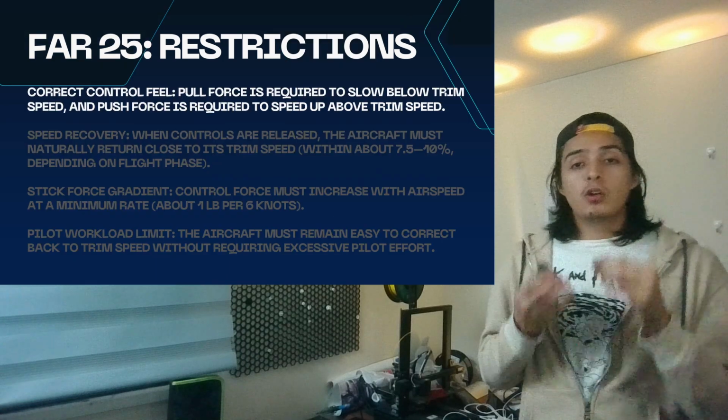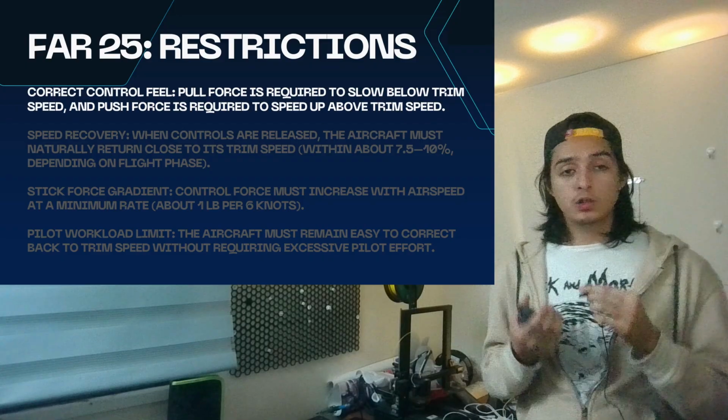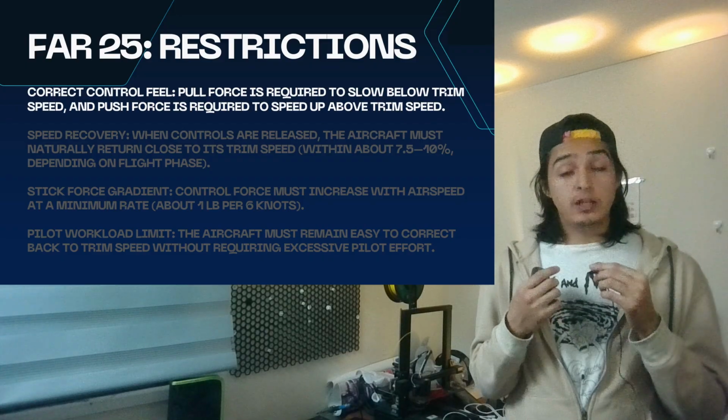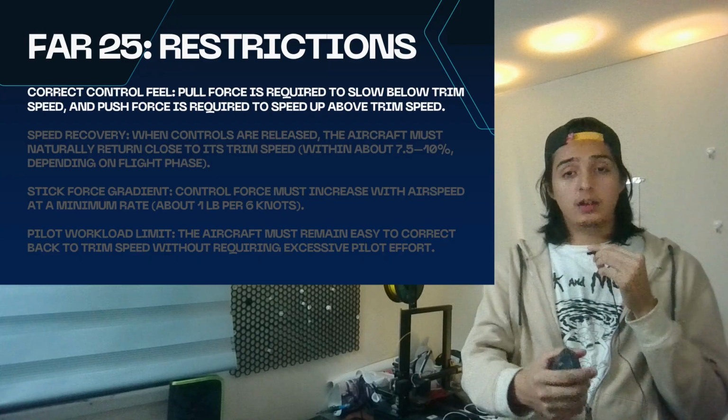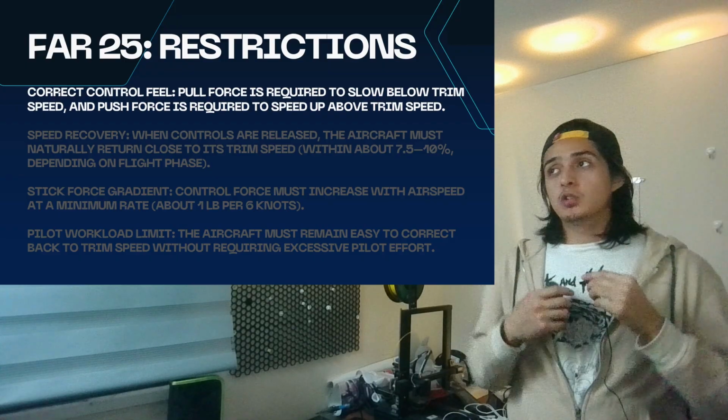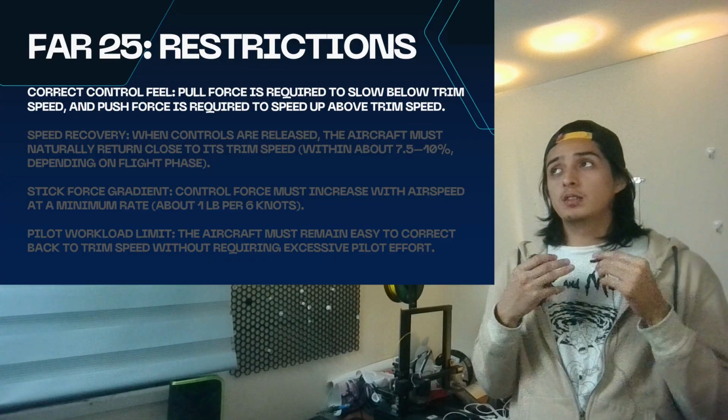So the correct control feel, in simple words, means that if the pilot wants to fly faster, he will need to push the stick, and if the pilot wants to fly slower, he will need to pull the stick. So this can be illustrated with this example.